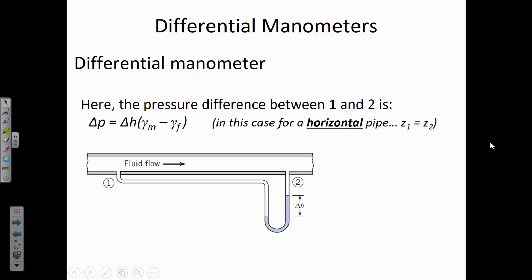Yeah, exactly. So there's enough pressure inside of this tube to push it more on the left than on the right. Now let me tell you something. The fluid isn't going through the manometer. The fluid is going through the pipe. We have moving fluid in the pipe, but inside of this manometer, conditions are static. So there's equilibrium inside the manometer. It comes into some equilibrium and then the fluid deflection stops. So we've got to be careful about that.